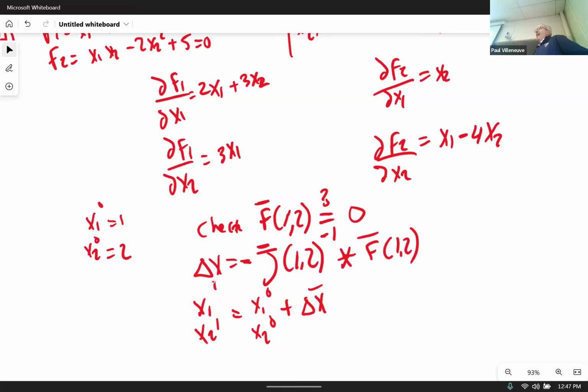If you don't have that, you can never really run a load flow because your system is not going to work. You're going to have too many line losses based on the scheduled and demanded power, and you're not going to have basically KCL. So having a slack bus means KCL is going to be met. Always, always, always. Those were the two.